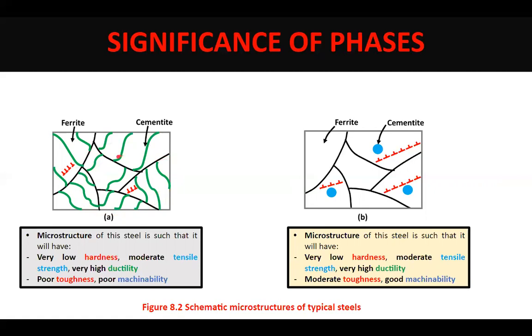Even if you talk about hardness, the shape is lamellar, but still the bearing area of the secondary phase is not great. So when the shock load comes, a large stress concentration takes place on this cementite, and again the cementite phase will develop cracks, which would initiate and propagate and lead to failure of the material. Now, machinability is largely dependent upon the secondary phase, and I said the secondary phase affects properties by virtue of its morphology. In order that these dislocations move and machinability becomes excellent, I have to do away with this lamellar morphology of the secondary phase.